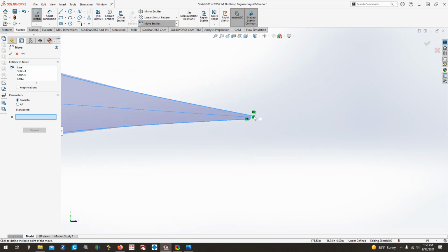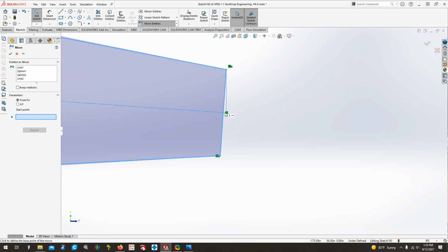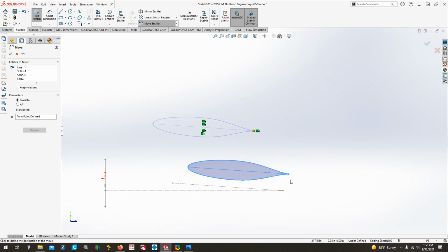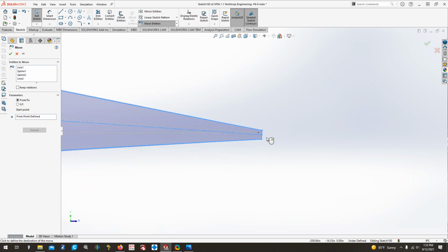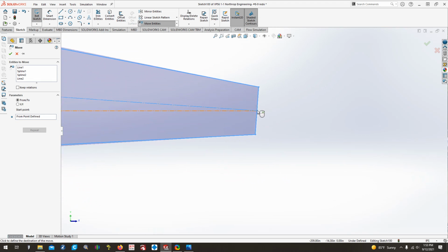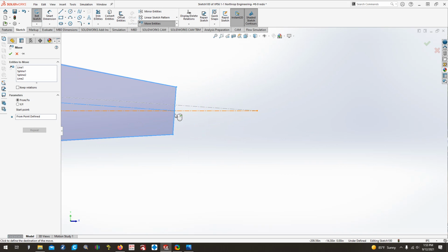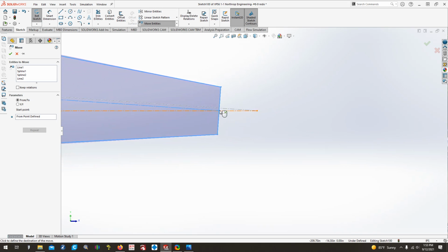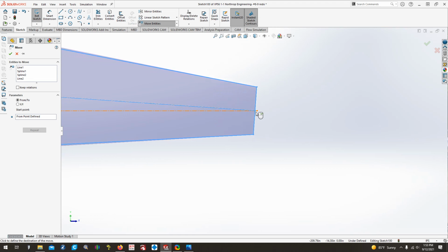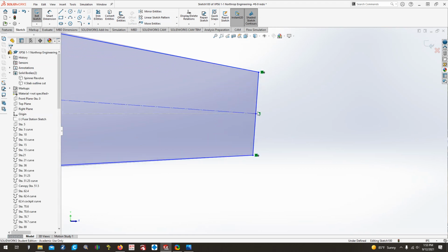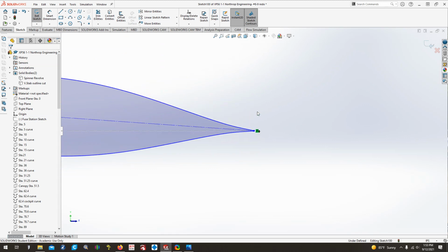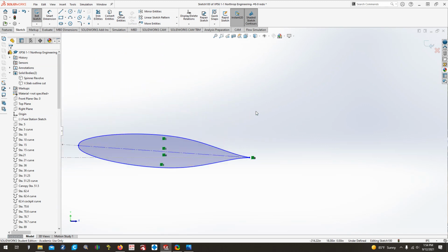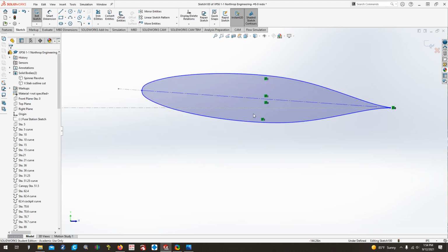You want to come up here, and you want to select the point of this chord line, which is the center line of the chord. You want to select that one. We'll zoom back out a bit here, and then we'll zoom back in to our reference drawing to make sure that we get it back where it needs to be. So we're going to drag it to where that horizontal line highlights orange in this case, and then we're just going to move it back until we get to the point, and boom, we're going to left click, and now it is in its proper location along the wing root at the fuselage center line.